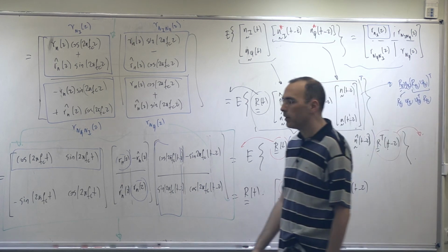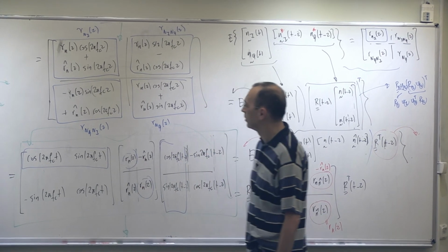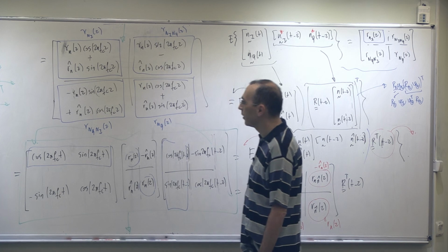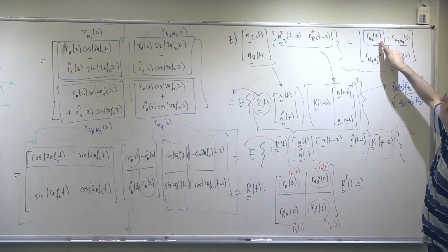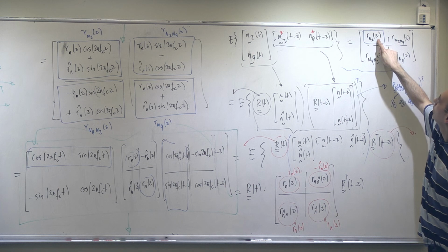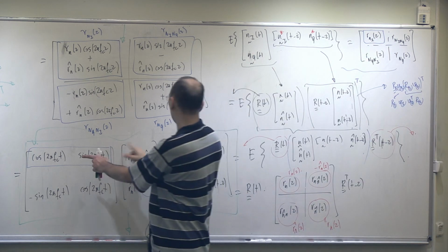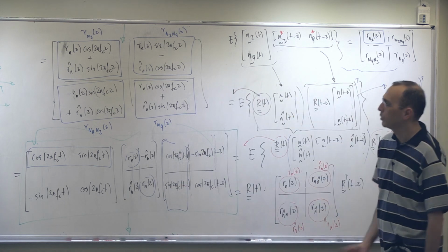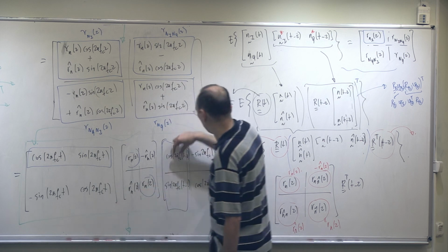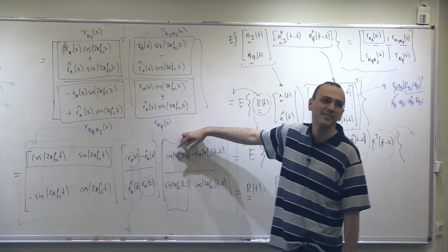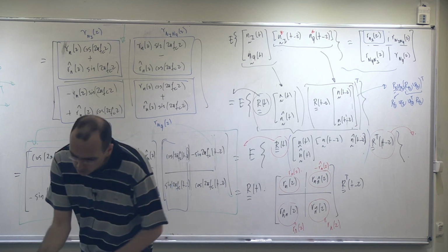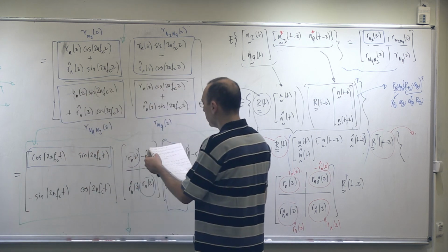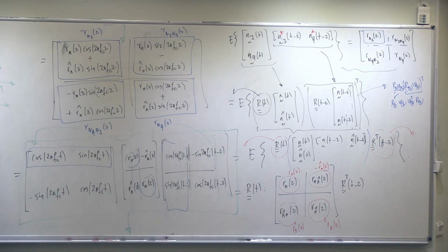And you can see that everything goes very right again, isn't it? These cosine expansions, these kinds of things, everything goes very right, and I'm getting a wide-sense stationary process. Do you remember at the very beginning we said that I'm writing this, and I'm hoping that Ni, Nq will be only a function of tau, but not t. So you see that that cancellation also occurs over here. T is cancelled at the very end. This minus that is free of t. That is the issue. You can do the other calculations and verify this is correct. But just to make sure that I'm not making any mistakes, let me write this point, and then in the next hour we will continue from that point.